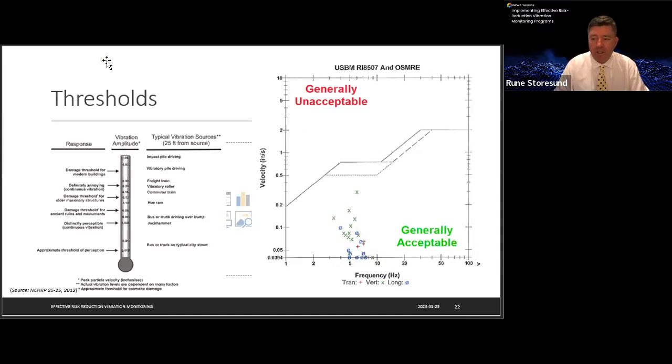I'm kind of a data collection person, so I would install them at both locations, the ground and the top. That structure is probably going to behave differently depending on where you are, the frequency of the vibrations, the durations, and if you can monitor the lower and the upper level, right? And if our pre-screening tells us that we shouldn't have a problem, I now have two data points that show I don't have a problem as opposed to just one. So I would go for monitoring both the upper and the lower.